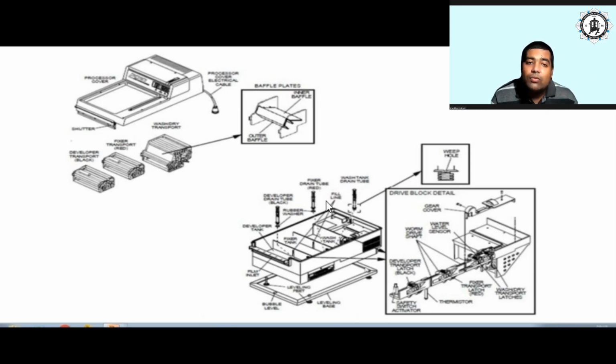You insert the roller through this end, and these rollers are also placed in these individual tanks. When they rotate, imagine there are two successive rollers and you insert a film between them. They will pull the film from the receiving end, the feeding end, and take it ahead. Where is the roller kept? The roller is kept in the tank. So what is kept in the tank? These development agents, fixing agents, stop bath agents, these acids, all these things are kept.